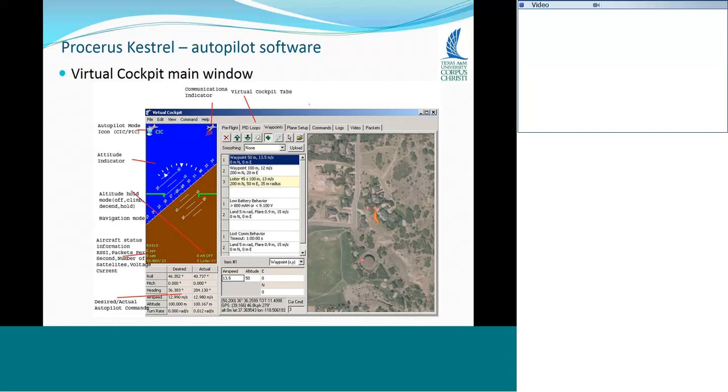And then on the left is basically the telemetry. This is telling you what the airplane is actually doing. Notice roll, in this particular case, the desired was 46.35 degrees, the actual is 40.7 degrees, so some error there, but showing what's commanded and what's actually measured. Okay. So this is what the pilot is looking at, and it has these different tabs, and you can do different things. So you can upload the waypoints, you can monitor the waypoints, and so that's what it looks like.